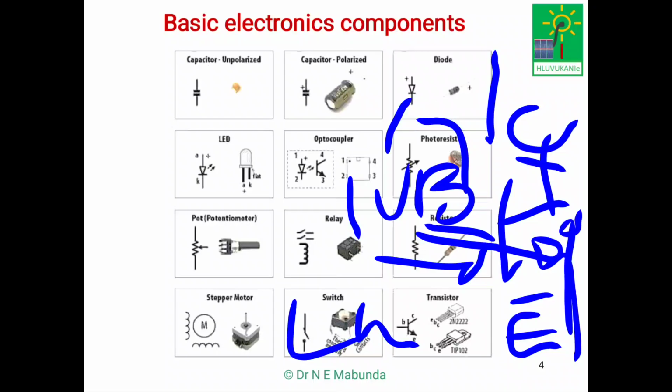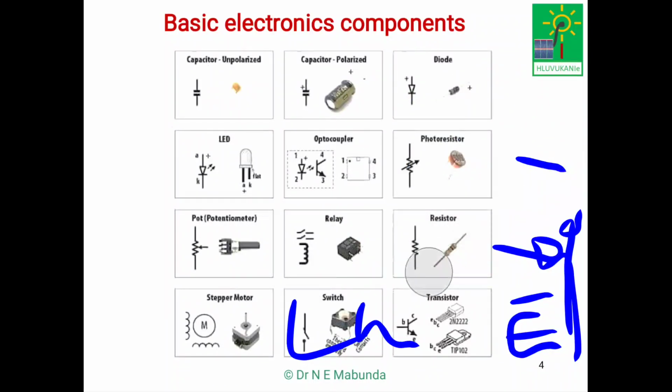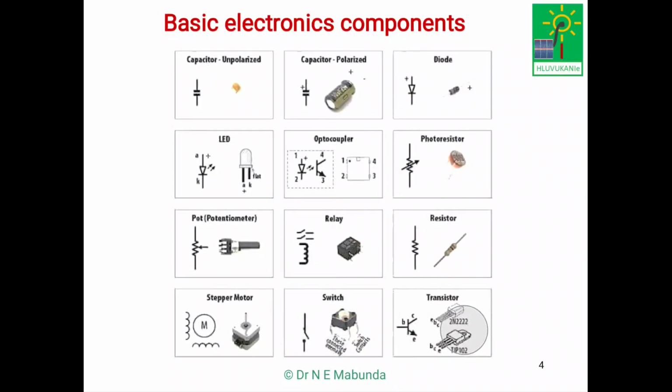Hence the term switching comes in there. Now, we can go back to that component we were in. If you look at that component, it's like an LED, which is coupled to a transistor. This transistor at the base, which I already mentioned, receives light, and that light controls the emitter collector current. But where will the light come from? It comes from the LED.